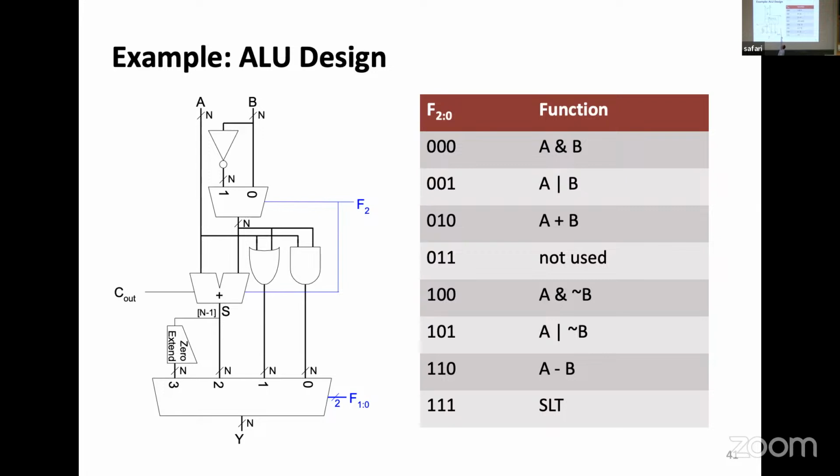Inversion, right? He looks at it, and if it is 0, B comes through. If not, it is inverted. And then the inverted one goes into the adder, makes it a subtractor, and comes out here. There is one strange thing happening here, and there is a carry out coming out from the adder. But other than that, this looks very, very boring, simple, things that we could really, with our knowledge, write very little code for. And this is the heart of the CPU we are building.